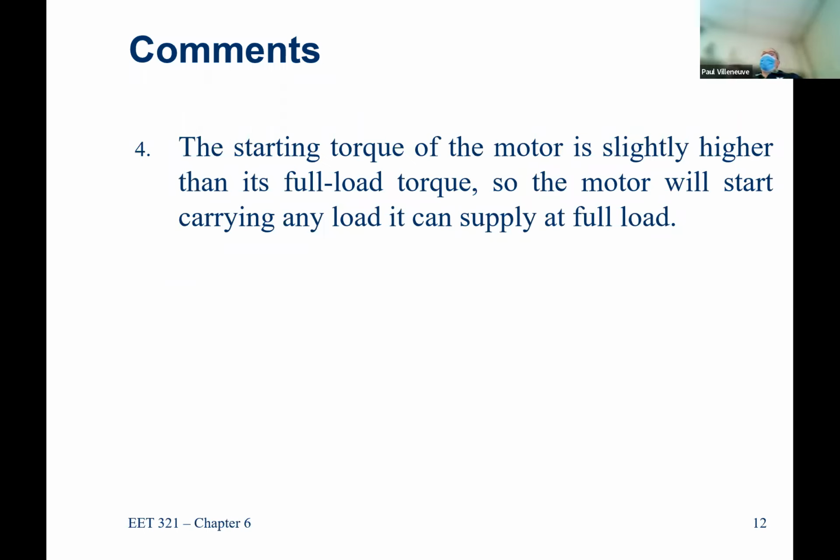Because once it's out of balance, remember it's spinning at 2, 3, 4,000 RPM. That's a tremendous amount of vibration. So any little bit of weight off will ruin it. Anybody here ever had their tires balanced? Driving down the road and the car is vibrating, and that's off by like 2, 3 ounces. And that's a 15-inch or 17-inch diameter tire. Think about that in terms of something that is running with a missing blade. It makes a huge difference.